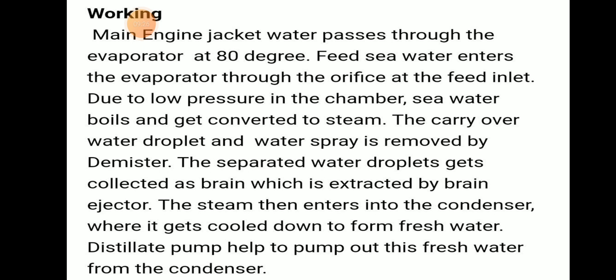Working. Here is the working of that. Main engine jacket water passes through the evaporator at 80 degrees Celsius. Feed seawater enters the evaporator through an orifice at the feed inlet. Due to low pressure in the chamber, seawater boils and gets converted to steam.